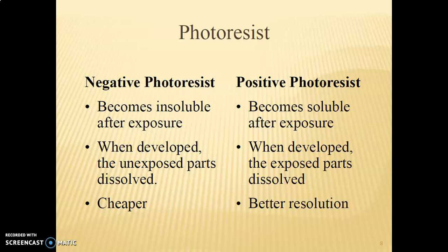It is cheaper and has better resolution. You have to identify, suppose you want to create a hole or a solid part, and from that you can select the negative or positive photoresist process.